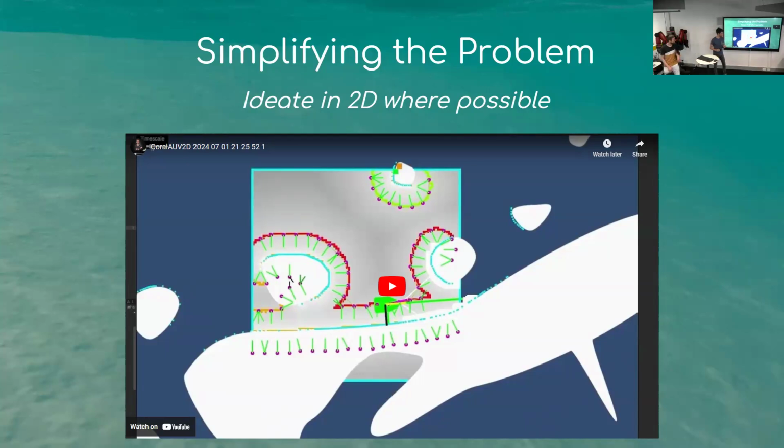So this particular project was the Coral AUV project. The idea is that we were attempting to follow the contours of a reef environment autonomously and detecting that reef as we went. We didn't have any predefined map of this environment, so we had to use whatever sensors were attached to the Coral AUV, which in our case were three ping sonars, single beam sonars, a forward-facing stereo camera and a down-facing stereo camera. Just using those sensors, can we follow the reef?